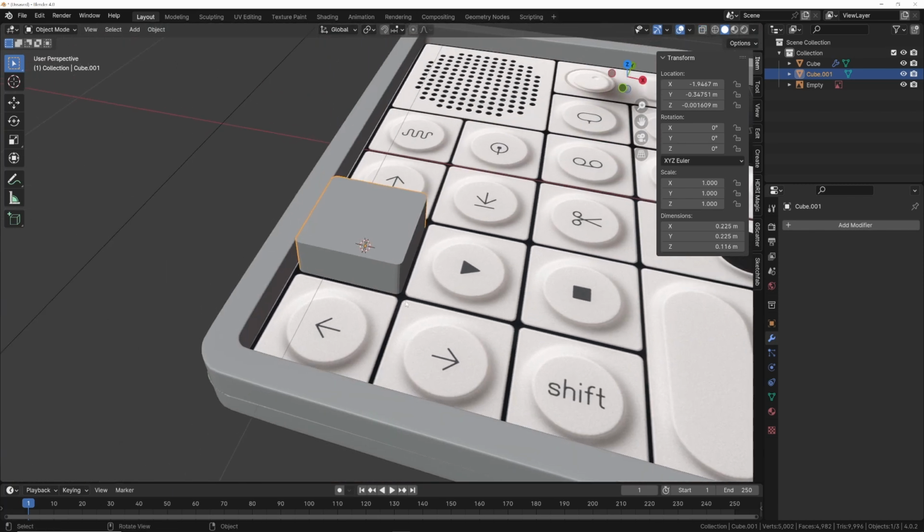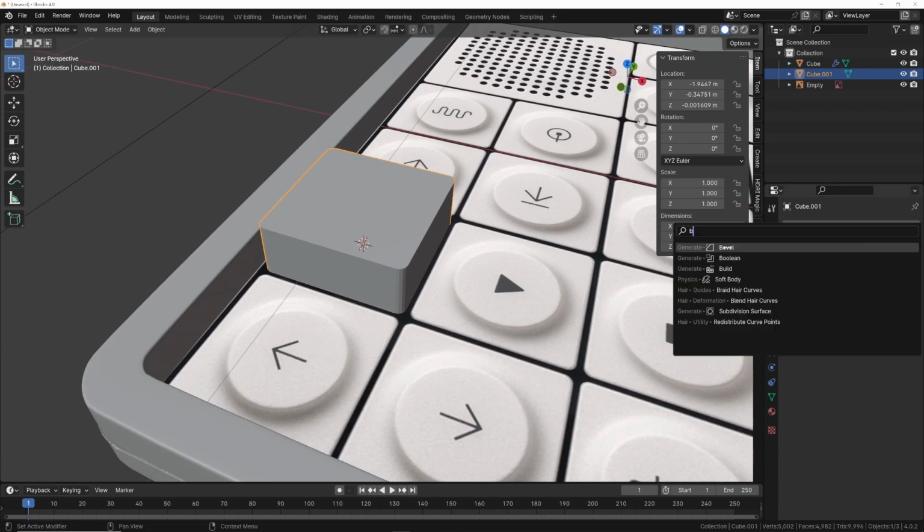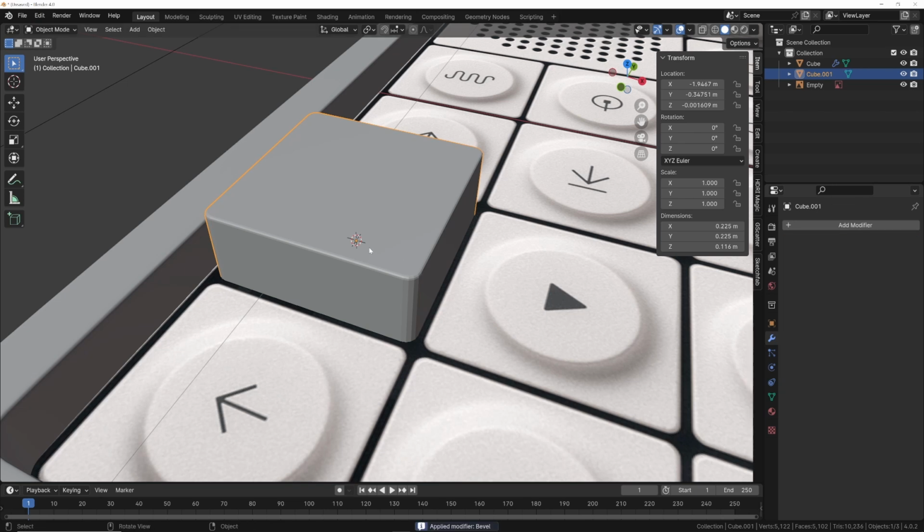And then I'm going to go out of X-ray mode now. I'm going to add this bevel on this top edge. We're just going to do that non-destructively. So add a bevel modifier, bring that way down, something that makes sense. Looks pretty good. We're going to add 3. And then I'm actually going to use this geometry, so I'm just going to go ahead and apply that by holding Control A over that.